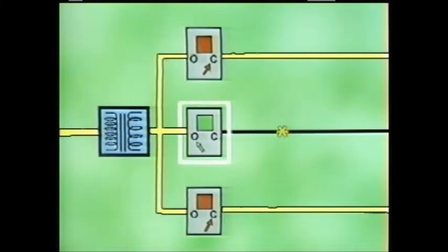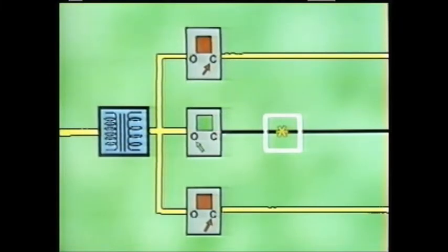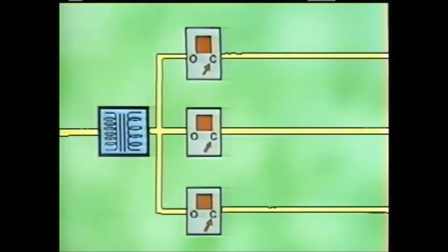In general, circuit breakers are designed to open and then close automatically after a specific period of time has elapsed. If the fault is temporary, as in the case of a tree branch swaying into a feeder, it usually clears fairly quickly. When the circuit breaker closes, service is restored and the system continues to operate normally.